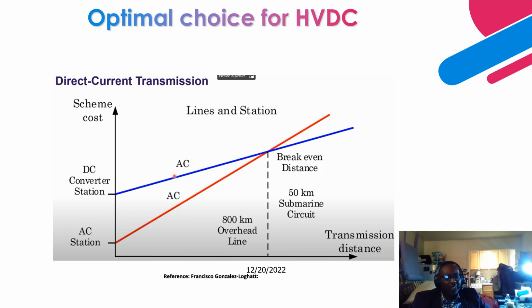The caveat is that HVDC has a much lower right-of-way cost for the transmission towers, and the tower cost is also much lower compared with an AC transmission line. Also, a DC transmission system utilizes fewer conductors: an AC transmission network utilizes 3 conductors as compared to a DC transmission system that utilizes 2 conductors.